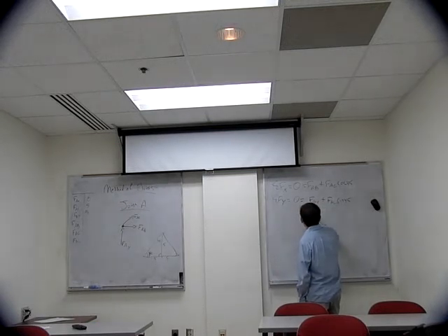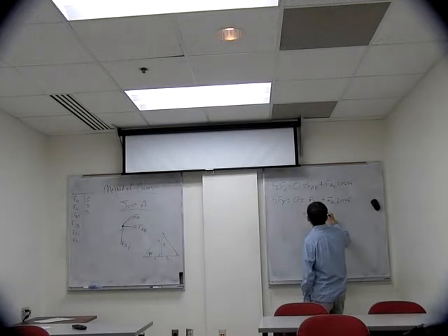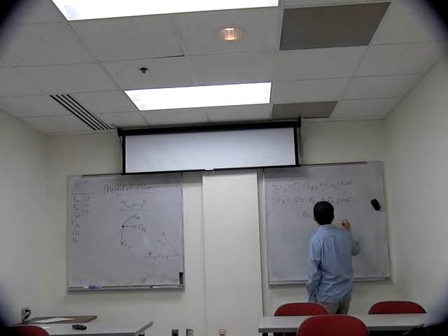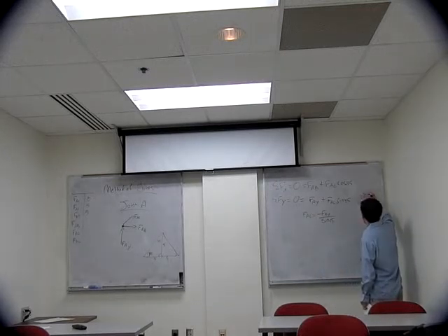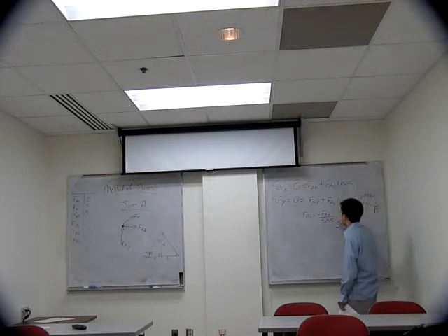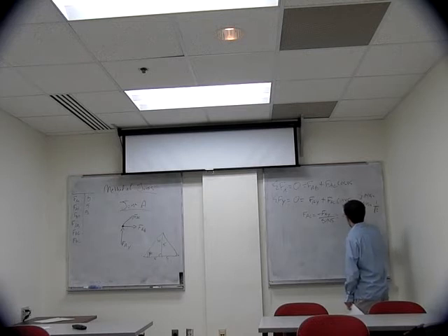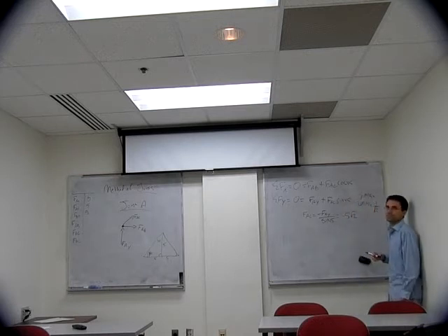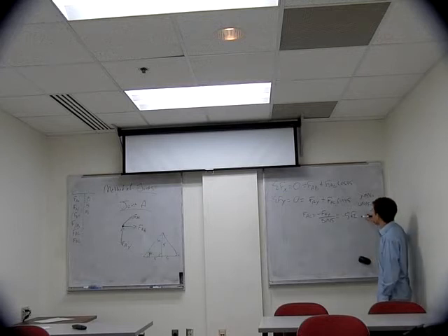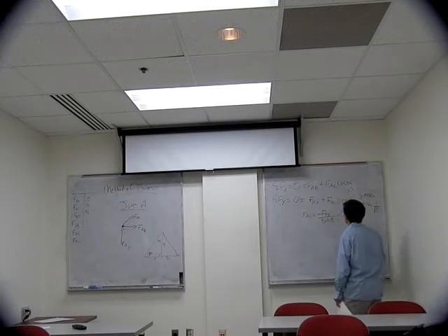So we have Fac is going to be equal to negative reaction force at A divided by the sine of 45. And we know that the sine of 45 is equal to the cosine of 45, which is equal to 1 over the square root of 2. So since we know Fay is 5, this is going to be negative 5 times the square root of 2. All right? We can use this, plug back into our summation in x to solve for FAB.